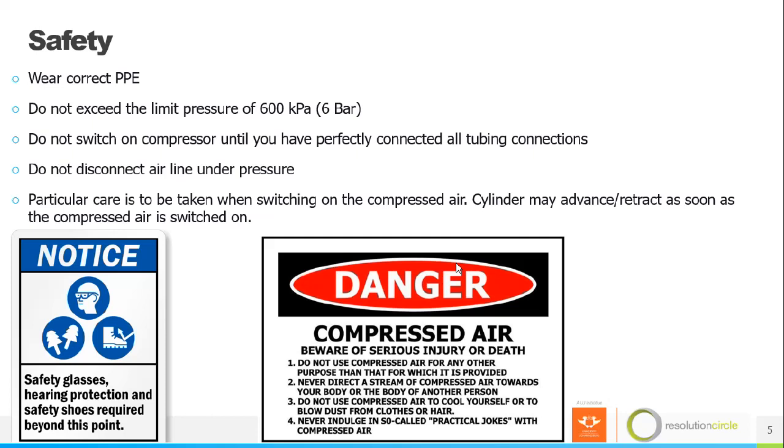Compressed air is dangerous. So guys, do not use the compressed air for any other reason besides the reason which it is provided for. Never direct the stream of compressed air toward your body or the body of another person. Do not use compressed air to cool yourself or to blow dust from your clothes or to blow your hair or even clean the workbench with compressed air. You should not do that, guys.